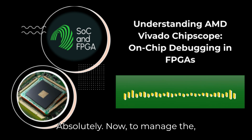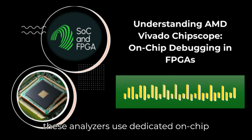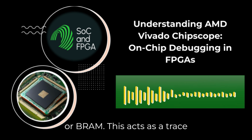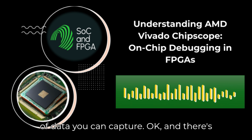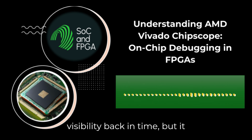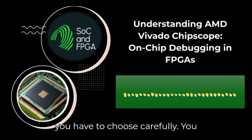Absolutely. Now, to manage the potentially vast amount of data, these analyzers use dedicated on-chip memory, usually FPGA block RAM or BRAM. This acts as a trace buffer. The buffer size, we call it data depth, determines how many clock cycles of data you can capture. Okay. And there's a direct trade-off. More depth means more visibility back in time, but it consumes more of that precious BRAM. So you have to choose carefully.